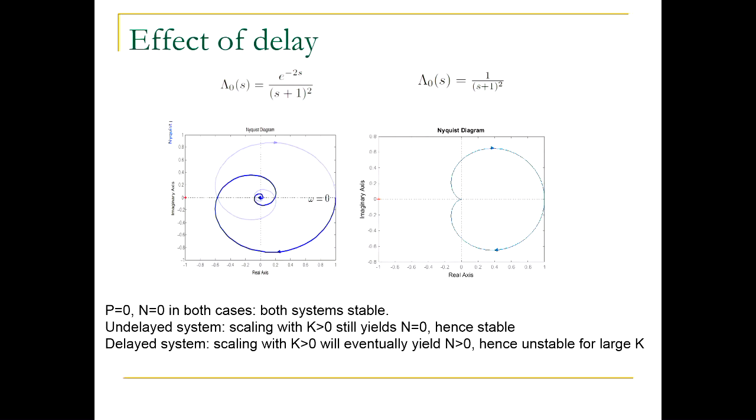Effect of delay: if I have two stable poles but I have a delay, you will see that the Nyquist plot will be like a spiral. Now the Nyquist plot always intersects the negative real axis. And obviously high gain will always cause problems. Because if you increase gain, the critical point moves here, so you start having lots of encirclements, and that usually causes instability. So even a small amount of time delay is very detrimental for stability.